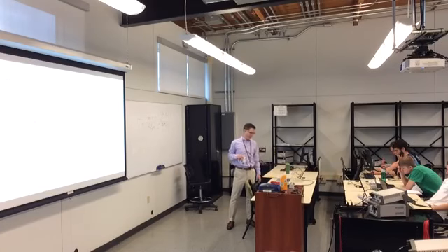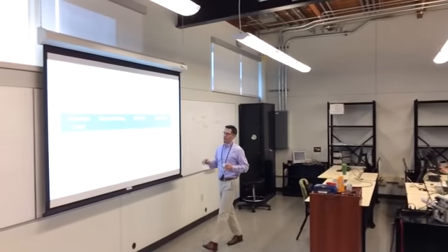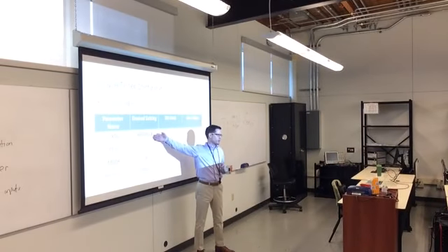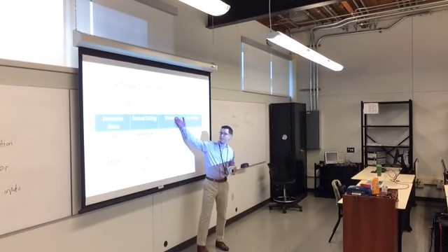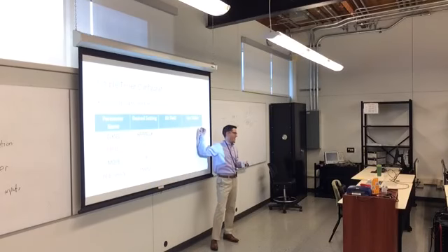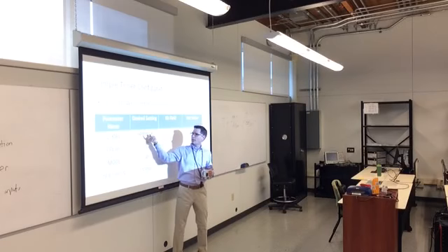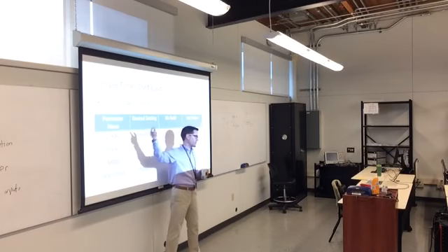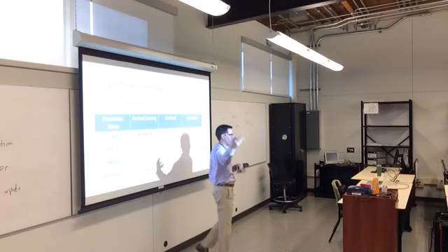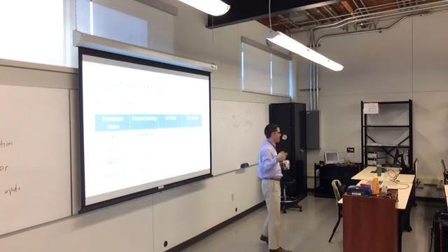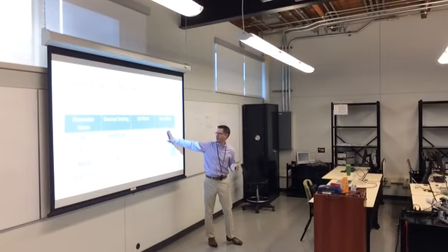But then once you know what things need to be set, you need to figure out what setting you want it to, what bits is this setting in that register, and then what hex value do you want to set it to. So is controlling the clock in this register bits 0 through 3, bits 9 through 12, like what bit range is it? And then once you have that bit range, what value do you set it to?